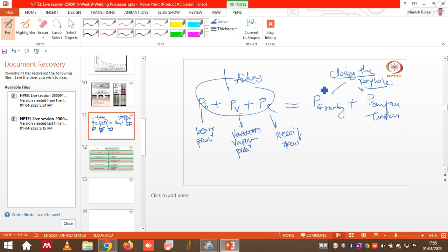So we already saw this during the arc welding processes, that liquid always has a certain surface tension value, and because of that, liquid always tries to contract its surface area, or it won't allow its surface area to change. So there is always the surface tension force, or we can say pressure. Because of that, the keyhole formation is actually restricted.